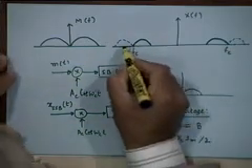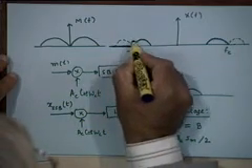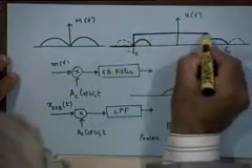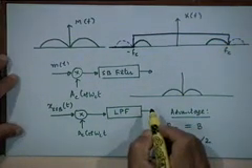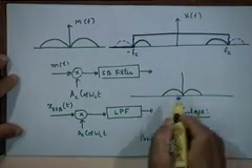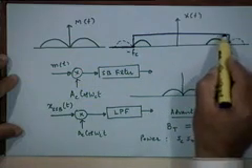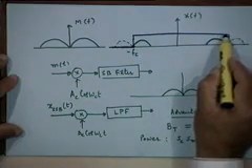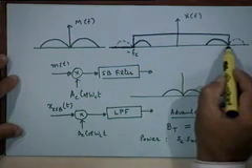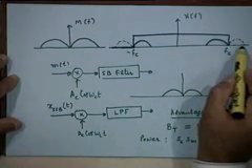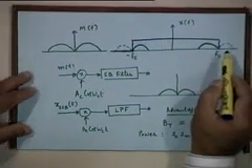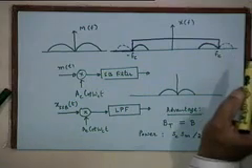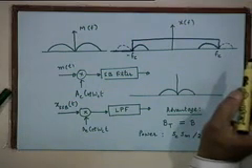Let's say you do it through a low pass filter, right? So what kind of transfer function would the low pass filter have? It should have this kind of transfer function, right? It should have a perfect transmission up to the carrier frequency FC, and a zero transmission immediately after that. And you know that such an ideal low pass filter is almost impossible to realize, very, very difficult to realize.